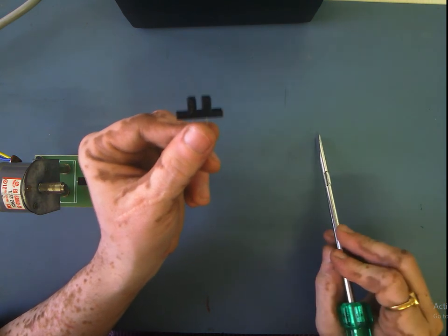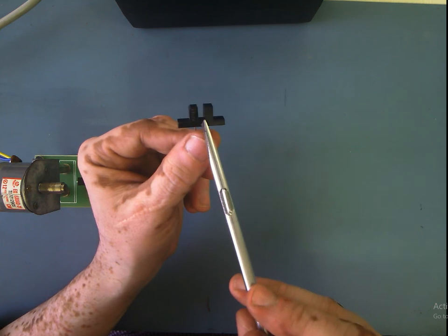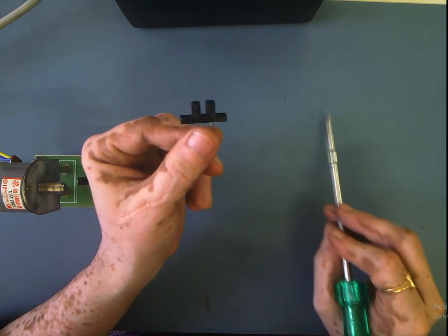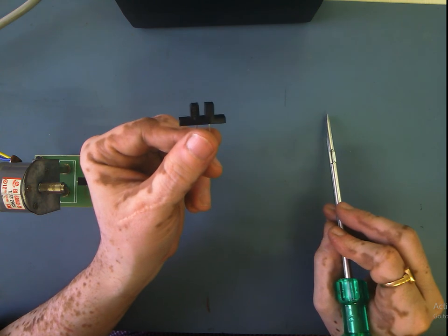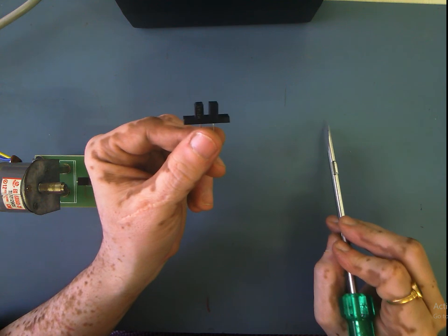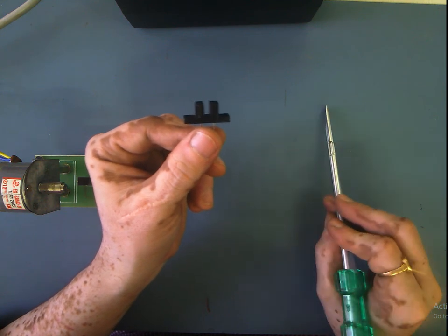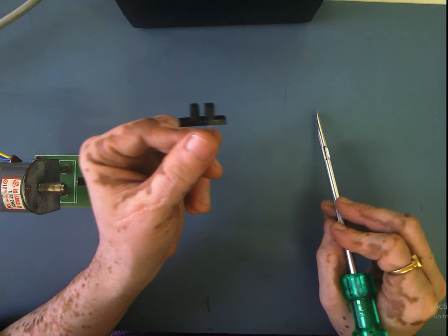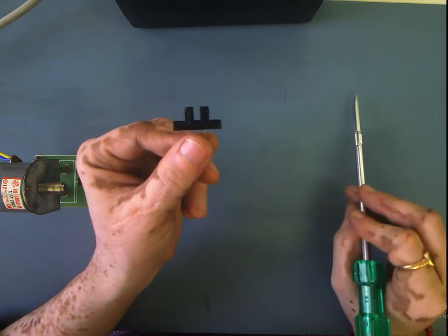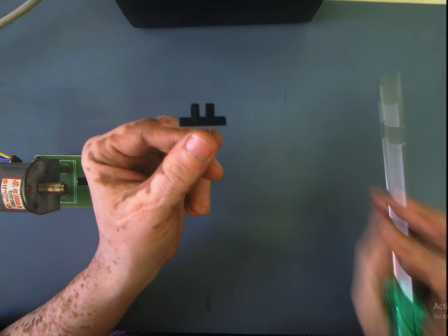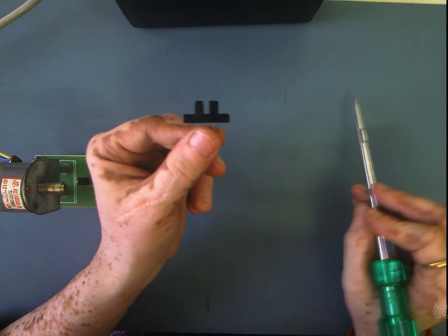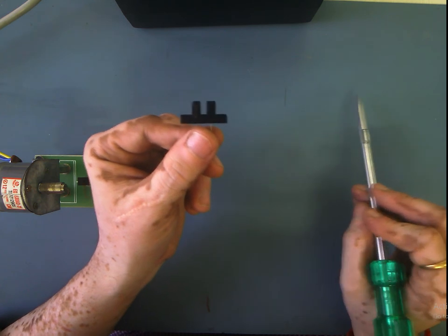If there is nothing in between and we measure the voltage across the collector to emitter, with a resistance connected from the collector to the supply, in this case let us consider 12 volt, the signal from the diode directly reaches the base of the transistor, and you will be getting no output signal because the transistor is conducting, and you can simply apply the KVL.